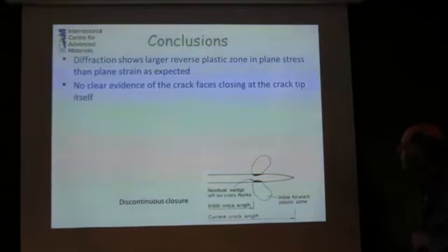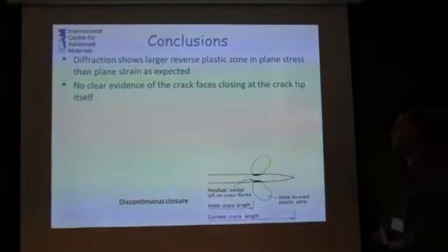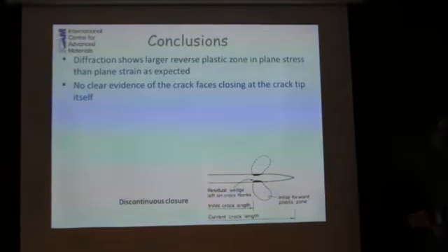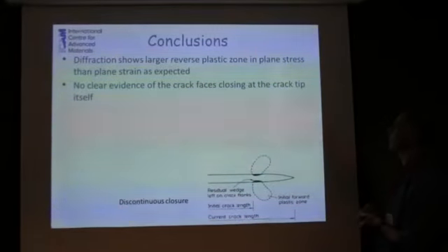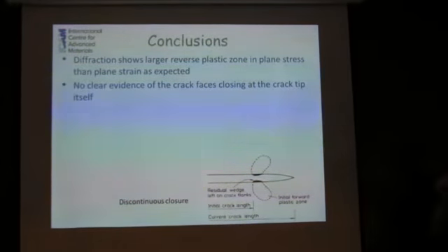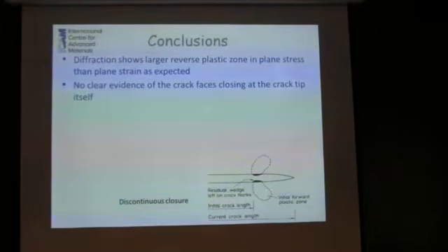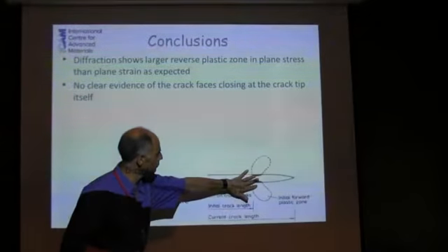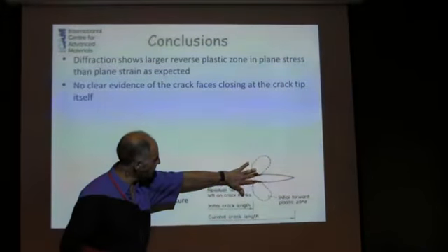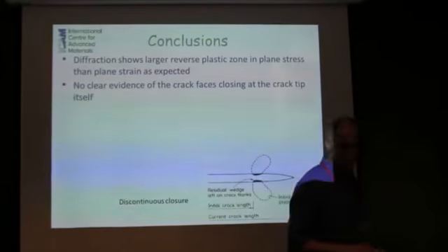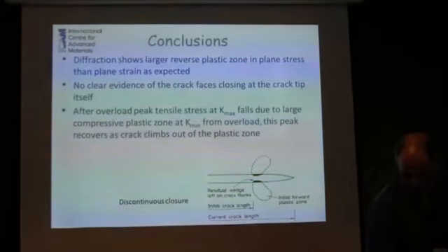Okay, so I just wanted to say I think diffraction shows a larger plastic zone in plane stress than plane strain. No surprise there. At the moment, we've shown no clear evidence of what you would call crack face closure, in the sense that right at the very tip, there's no real clear evidence that the crack is doing that. We haven't yet been able to show that. We need to go back and work harder at working out exactly where our crack tip is. But we do get this kind of discontinuous closure where you get a meeting of the crack faces far away, further away from the crack tip where the overload took place.